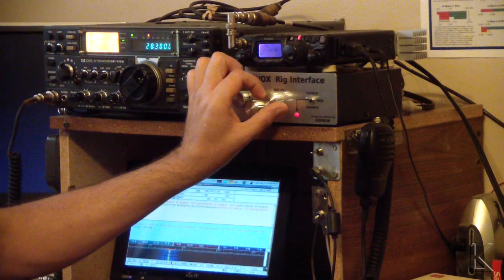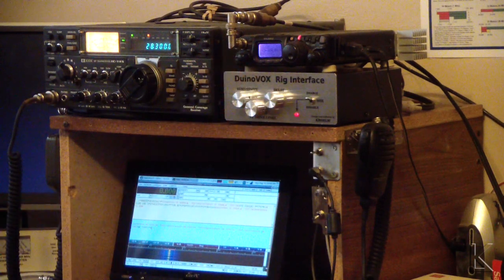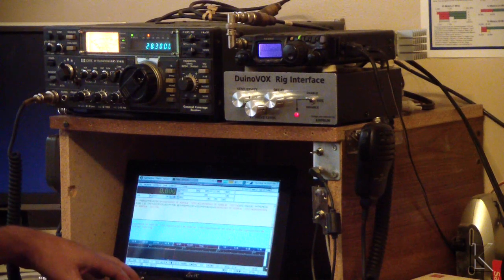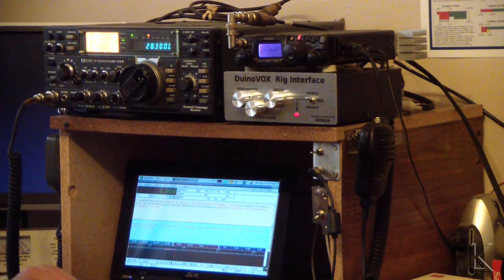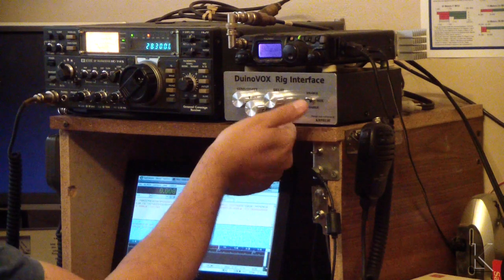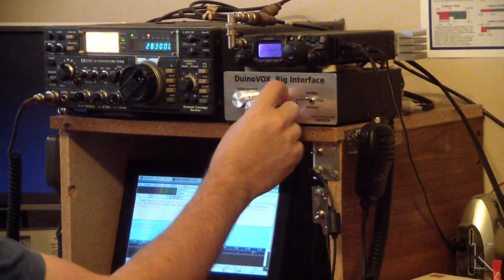I could actually increase the delay to a maximum of 2 seconds. And you can see it's not dropping out at all now because we've got a 2-second hang time. So it really depends on how you want to operate, how you use that delay control. Now you can see there was 2 seconds after that last dit before it dropped out. And I'll show that here. I'm going to send an E, so we'll hear 1 dit, and then there should be a 2-second drop. There you go. So that's how the delay control can be useful if you're sending keyboard CW.